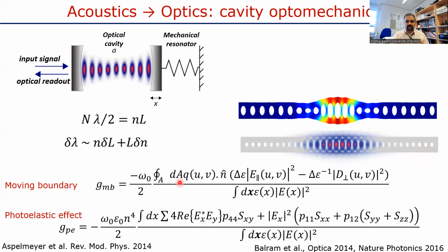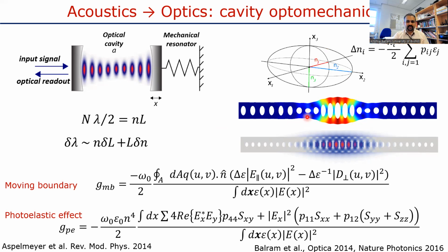And in some sense, modern acousto-optics, or this field of cavity optomechanics, relies on finding cavity geometries in which you can confine light and sound deeply at the wavelength scale and engineer very strong acousto-optic interactions. So the prototypical example of these devices are these 1D optomechanical crystals, in which you can confine both light and sound down to the single wavelength scale.